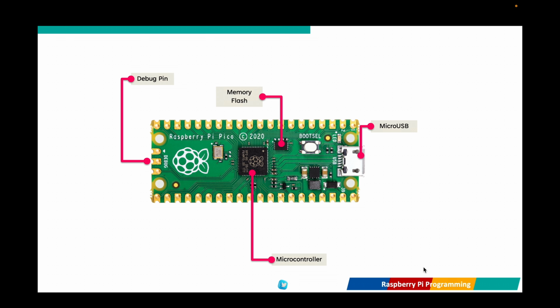The Raspberry Pi Pico includes a USB 1.1 port which serves two functions. Programming interface: this is where the Pico can be programmed via USB by drag and drop of UF2 files. USB device or host mode: it acts as a USB device like a keyboard or mouse, or even a basic host in some applications.